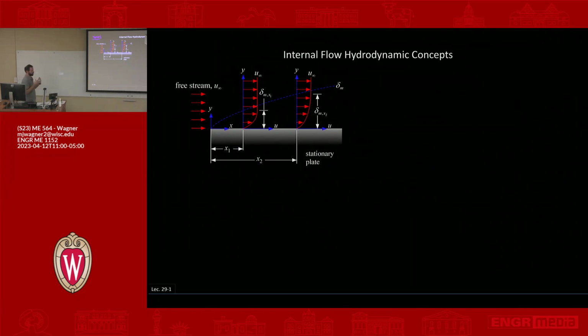It's like our infinite plane wall or semi-infinite plane wall analogy. In that situation, if you applied a heat flux on the boundary of a semi-infinite plane wall, it would just continue to grow, right? Nothing would stop it. It's the same thing here. You have this diffusion process that continues to grow. But as we said, eventually it would either become turbulent, or what we're going to talk about today is that the boundary layer gets to a point where it starts interacting with other boundary layers that are equally growing in. That's just what internal flow is.